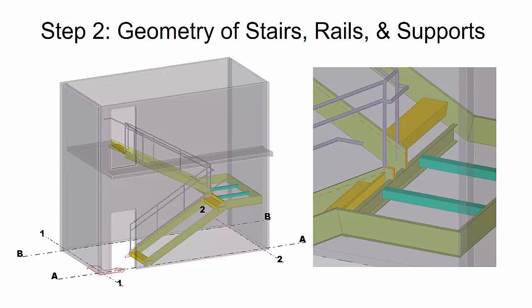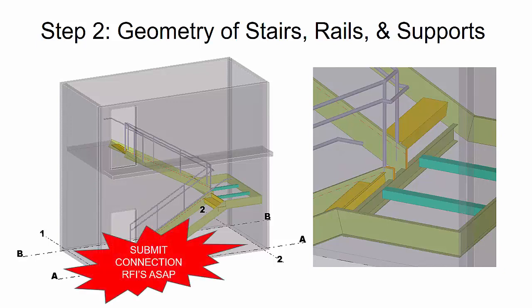And I start looking at the primary post locations and I start seeing how the landings and things might work based on the geometry. This is where I start to identify where I may need to move posts to work with my stringers and my guardrail system to work together. I might see the transition points between the one leg or flight of stairs to the other. I might see here on the landing steel that it may not work with the stringers that I want to attach to, and I've got to do something more creative or talk with the design team and the engineer.